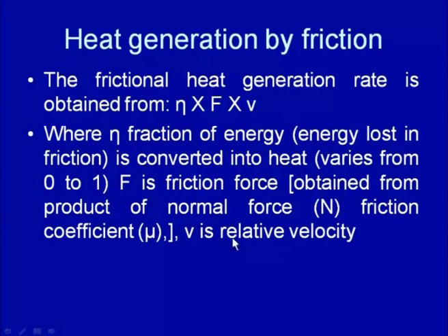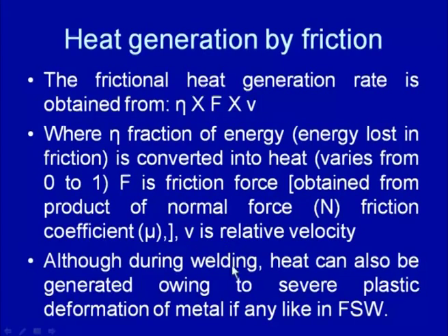For example, frictional heating is very effectively used in the friction welding process, the friction stir welding process, and the linear friction welding process, where a very high rotational speed is used between the mating components, or between the tool and the workpiece being joined, so that the frictional heat being generated can be localized significantly, and thermal softening can be done.